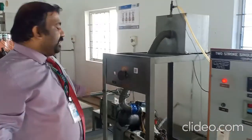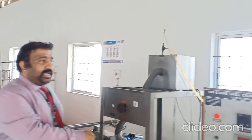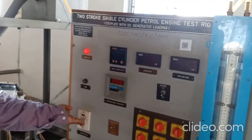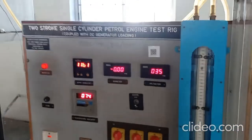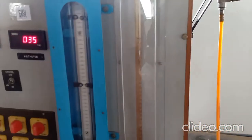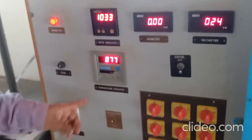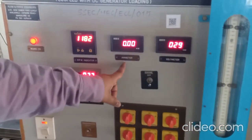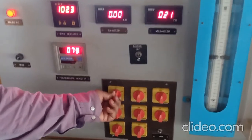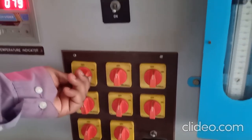We are starting the engine by kicking it, and here is the speed, and this is the main switch. If you want to use it, we have to switch this on, and then we will get the readings. These are the manometer readings, and this is the fuel tank. The fuel is going to pass through here. If you switch it on, the fuel enters the engine. And these are the RPM, ammeter and voltmeter readings. Each knob is 250 watts. Suppose you switch one on, then 250 watts of power is supplied. Like that we have to switch them on.